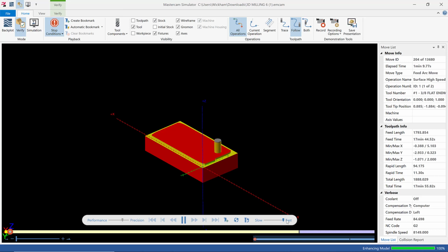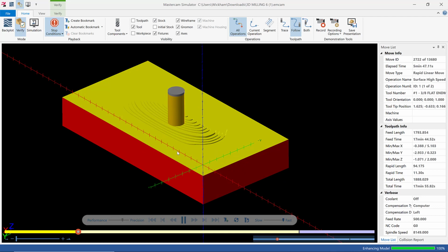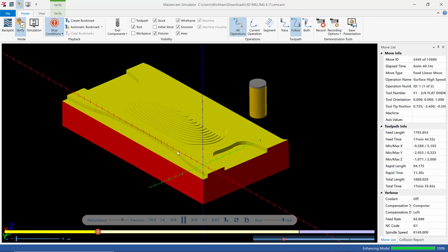We'll see what this semi-finished toolpath looks like. You see I have my precision set up a little bit higher, so that's why it's acting a little notchy. But that'll help us avoid the weird transition between the red existing stock and what looks like it's going to be a light blue or light purple semi-finished toolpath.